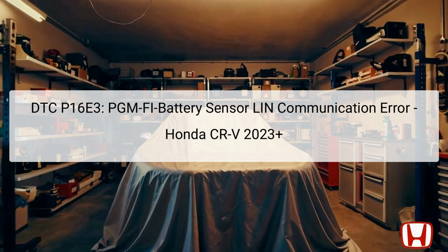The 12-volt battery sensor plays a vital role by monitoring the battery state and communicating critical information to the PCM. When there is a disruption in this communication, the PCM triggers the P16E3 error code to alert the technician of potential underlying issues.